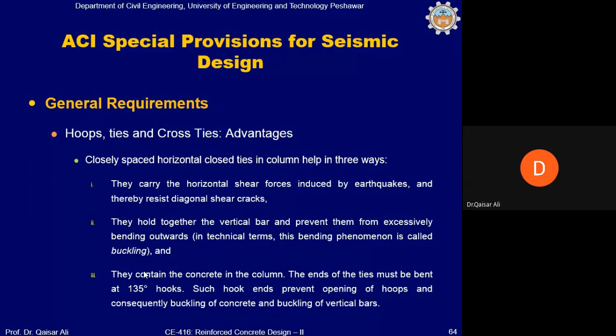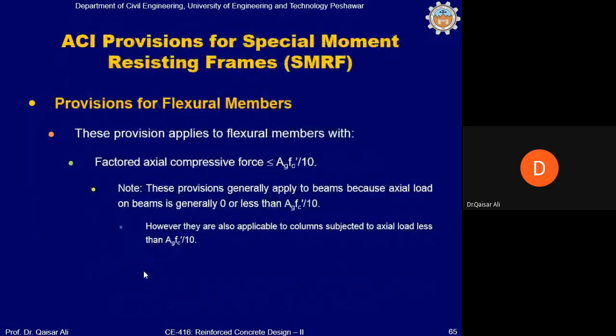From 3000 psi concrete, if you confine this, you can get a strength of 5000, 6000 psi or even more than that, depending on how the confinement has been provided. The confinement can increase the concrete compressive strength. Okay, this will also help in increasing the concrete compressive strength.